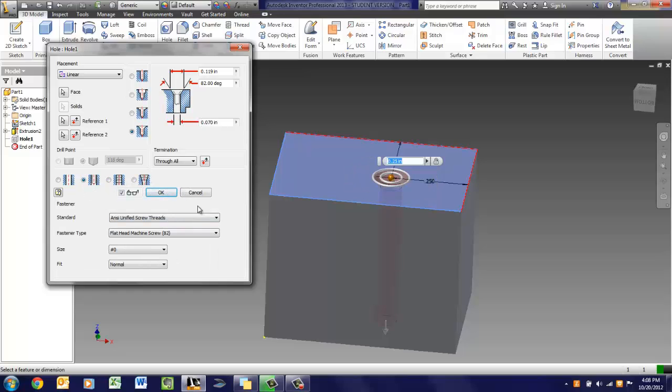And again, you'll be told what you need to do and given more information, all the information you need to identify what you'd be using. Okay. In the allowance fit, this is just a little bit different. I know this is getting a little bit long, but as far as the clearance hole here, okay, it's going to be based on a certain thread size, but it's going to give a little more distance, so that the screw or bolt, in this case you'd be dealing with a bolt, would fit down through without touching the side.